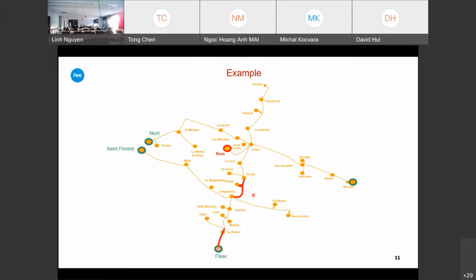If there is a lot of power, but not so much, then line opening may be useful. Or you may have this line opening in this small area when you have not so much wind farm producing now, but a large flow coming from Spain to Belgium, going through there, and there is so much on the 400 kV grid that a part of it is coming through the 90 kV. Normally you keep the lines connected, so closed means connected, they are operating. In some cases, it may be better to open them.